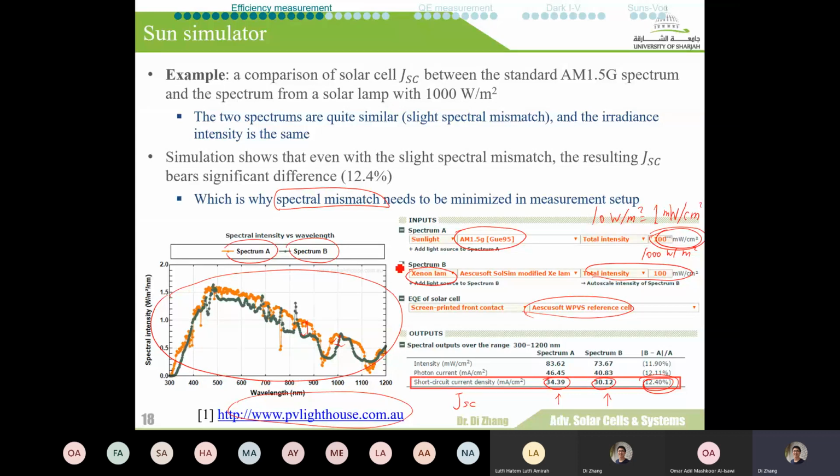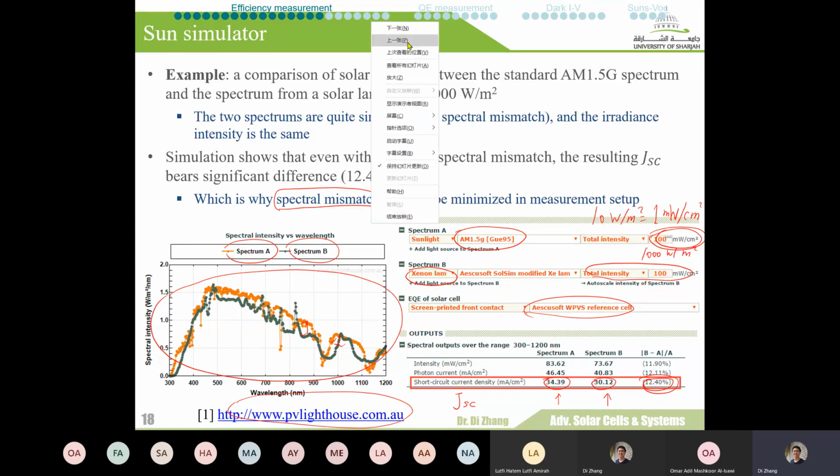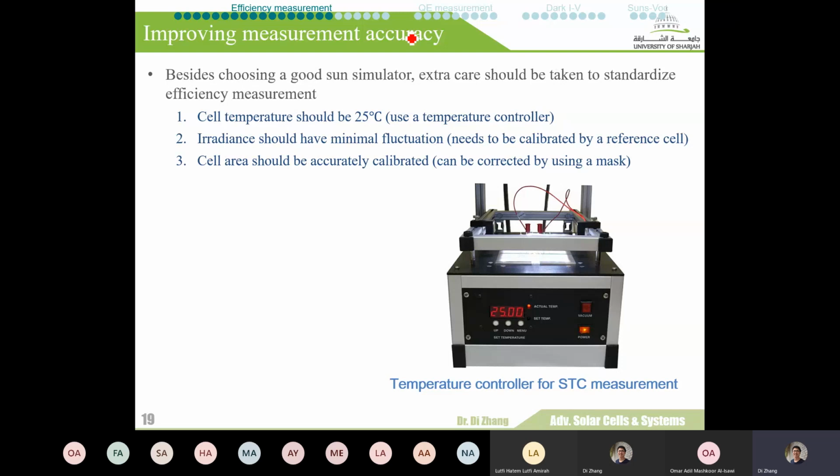Okay, if you have any senior projects that involve solar PV, this could be useful. So that is actually the solar simulator requirement. Now, besides the solar simulator, remember in the STC, we also have other requirements. Specifically, we mentioned that the solar PV temperature should be 25.